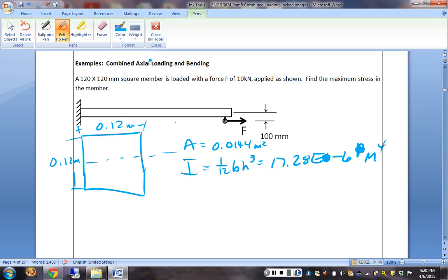What do we have to do? We have to do a statics problem. Now that we're moving into this, I'm cutting out a little bit of the detail. I will say that it is probably a good idea for the exam and for moving forward in these problems, refer to the sign conventions on page 4-4, because remembering which way the force is to be a positive shear or a positive bending moment is going to become more important as we're piling more things on top of each other.